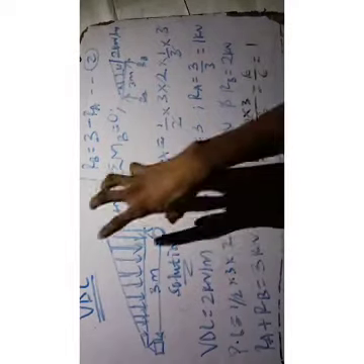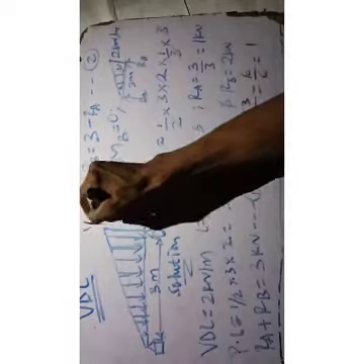You take the moment about point B using 1/3 of the length or 2/3 of the length. So what you do next is you do the diagram, then you take your moments about point B. That will be 3RA equals clockwise equals anti-clockwise. 3RA equals half base times height times 1/3, because you're taking moment the bigger parts, 1/3 of the length, simple.